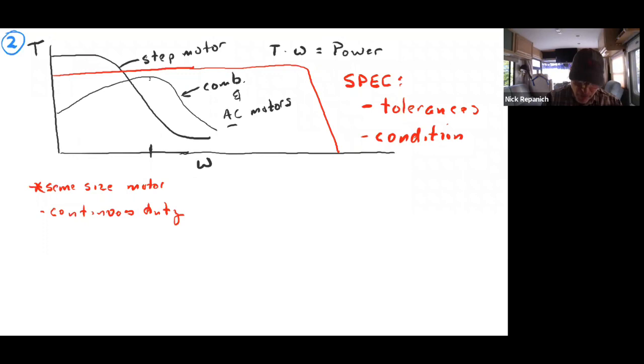The stepper motor has lots of torque at zero speed. For the amount of size it has, there isn't a device that has more torque at these slow speeds, but it's got a complex magnetic structure, and it's lossy, and it loses its torque very quickly, as compared to a servo.